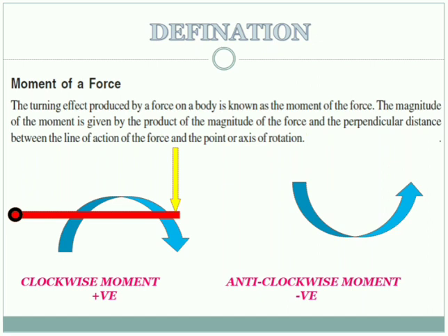So the force magnitude, what did we say? F. Let the length of the beam be L. Then as per the definition of moment, the magnitude of moment at point O, this is your point O. About this point, the magnitude of moment will be the magnitude of the force, which we have taken as F, times the perpendicular distance.